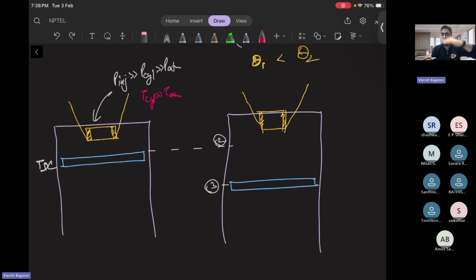But in the meanwhile, the piston is not at the same position. The piston is also moving. It's a very fast process, but the piston is also moving from point 2 to point 3, and similarly the spray of the diesel is also coming here. So that is why the fuel injector provides the diesel at a constant pressure, and meanwhile the piston is also moving. It is not a heat addition at a constant volume.